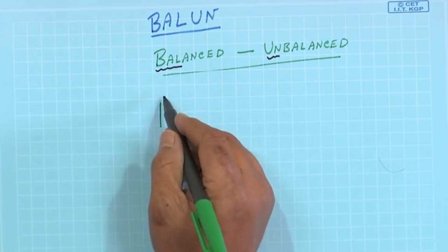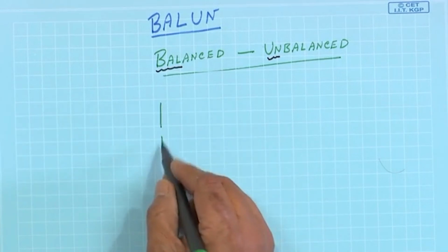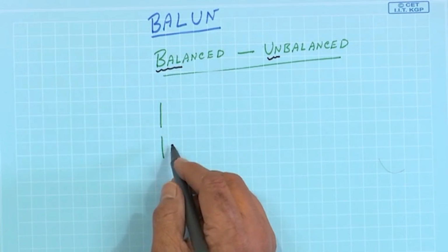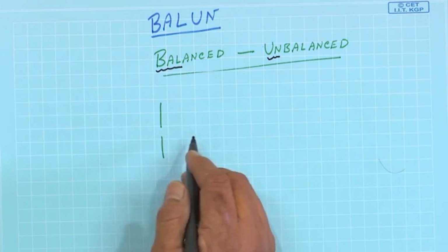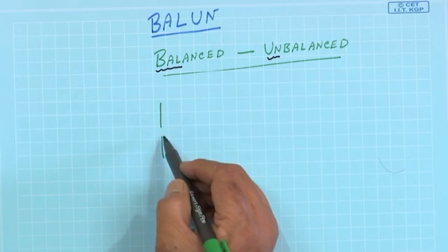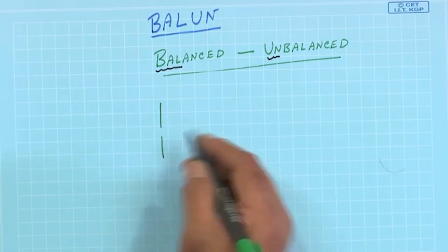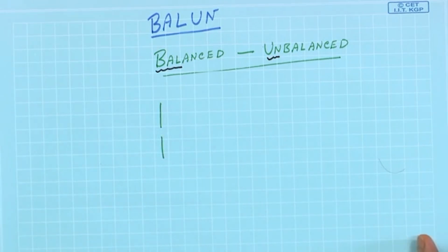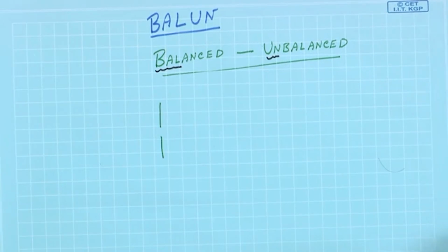If these two poles assume the same current distribution, the radiation efficiency is maximum. The current should go in one direction and the same current should return in the other one. The goal is to feed the antenna in such a way that these two poles have exactly the same current distribution, that is the even symmetry.